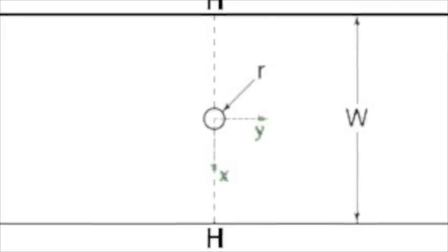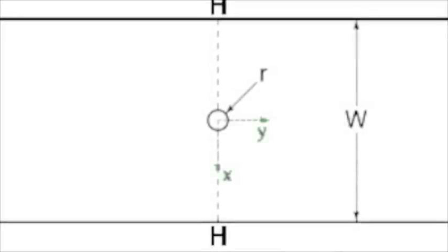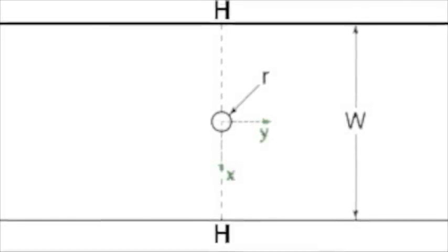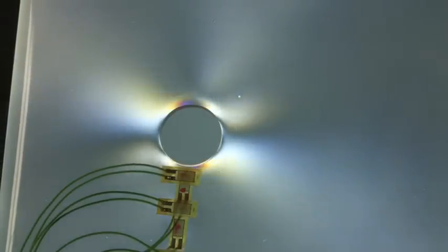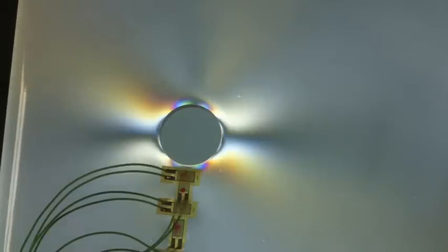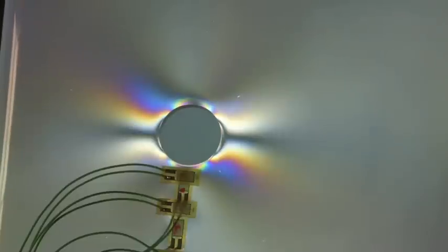Experimental. The next step was to physically strain the plate and test the theoretical data against the acquired data. The lines of different color represent changes in the concentration of stress. The closer the lines, the higher the stress is close to the hole. Away from the hole, there are no changes in color, which corroborates the theoretical prediction.